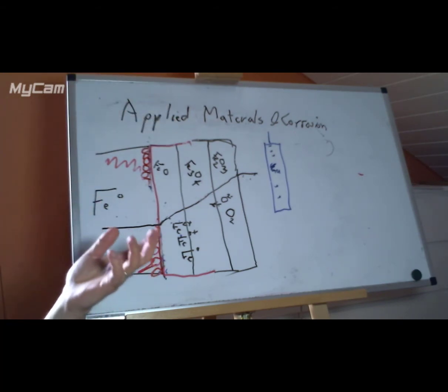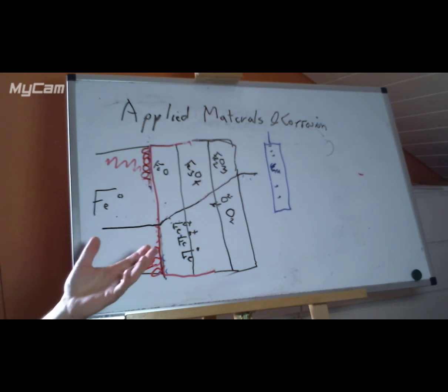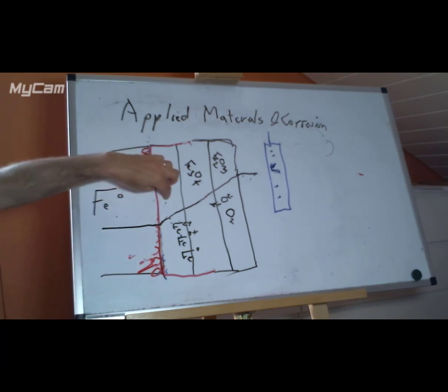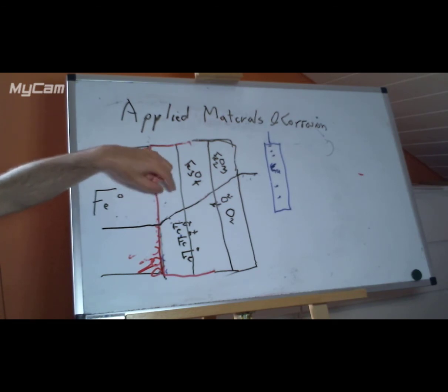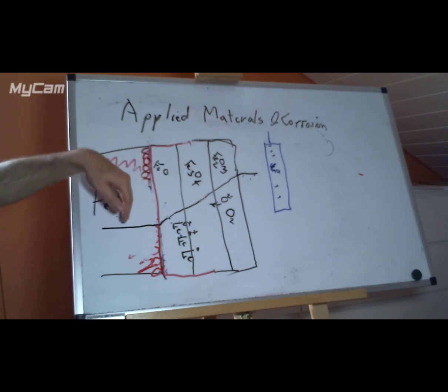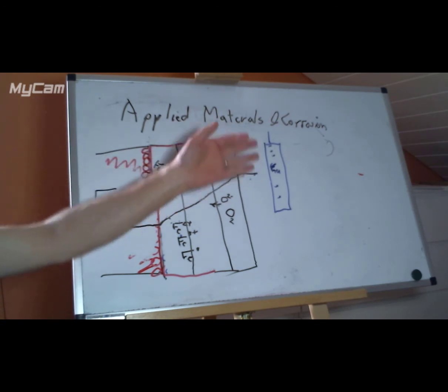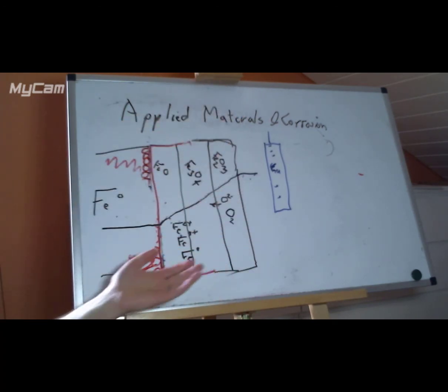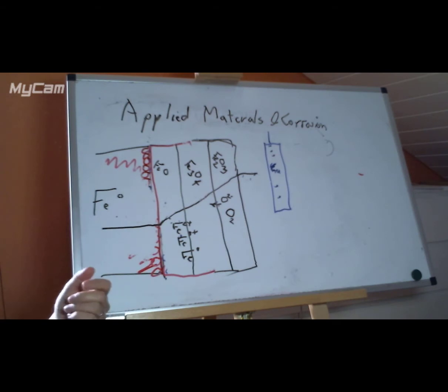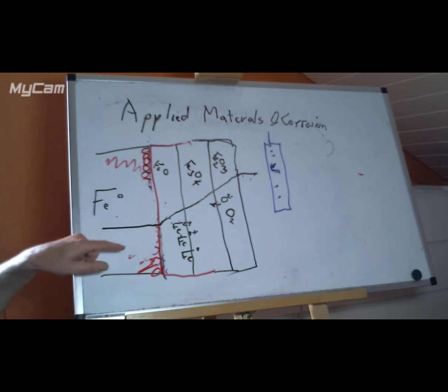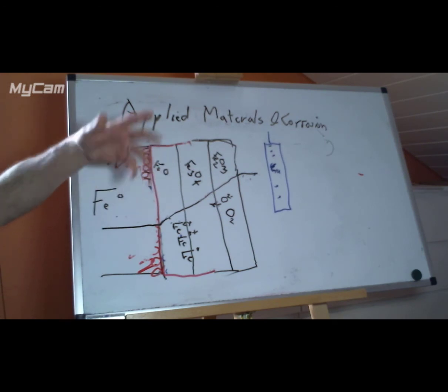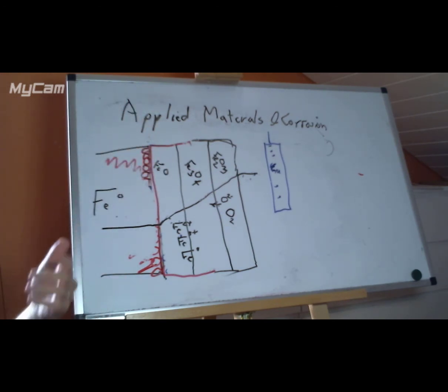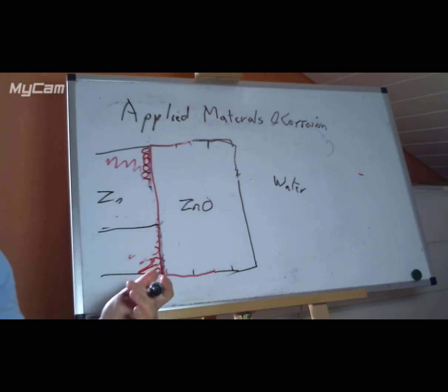So thermodynamically, it's kind of temporarily stabilized. Locally, it's thermodynamically stable, but it's only thermodynamically stable because the iron is drawing it down and the oxygen is pulling it up, so the whole system is not stable. It will eventually oxidize. It just takes a very long time because the resistivity of this oxide layer is such that everything is locally happy, so very little happens. It's very slow. So what happens if we go into contact with the solution?